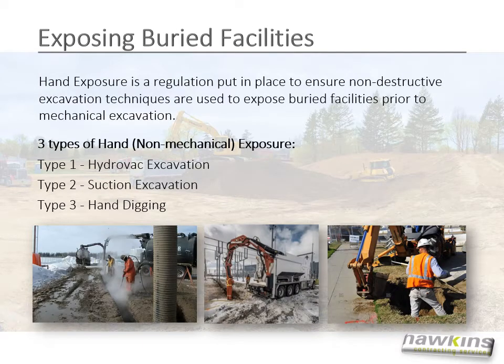When exposing buried facilities, you must use hand exposure. Hand exposure is a regulation put in place to ensure non-destructive excavation techniques are used to expose buried facilities prior to mechanical excavation. The permissible types of hand exposure or non-mechanical exposure are hydrovac excavation, suction excavation, and hand digging.